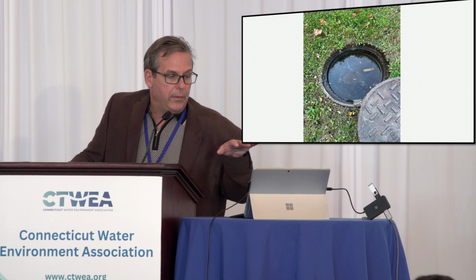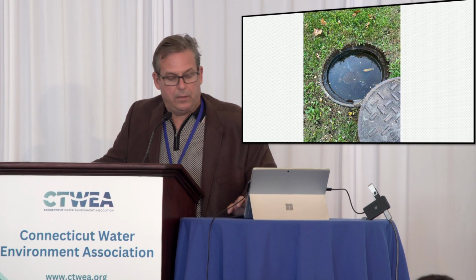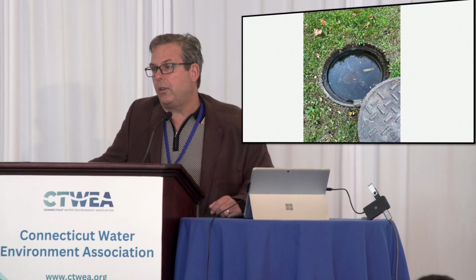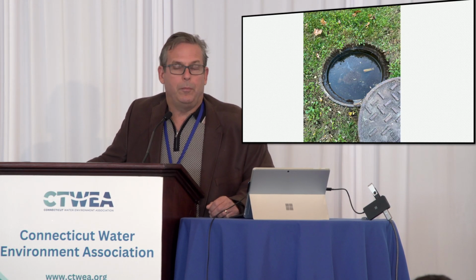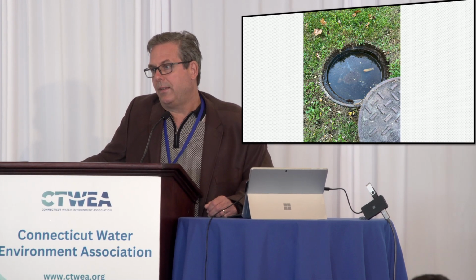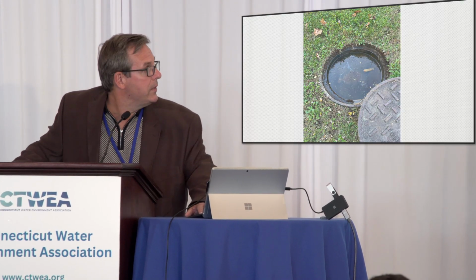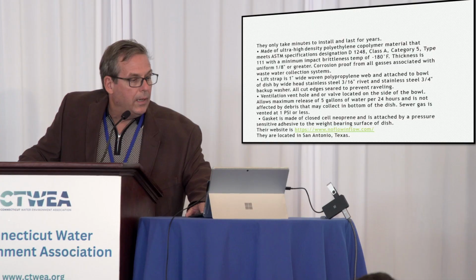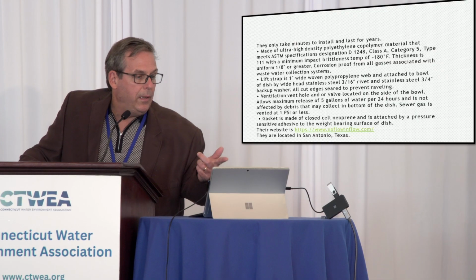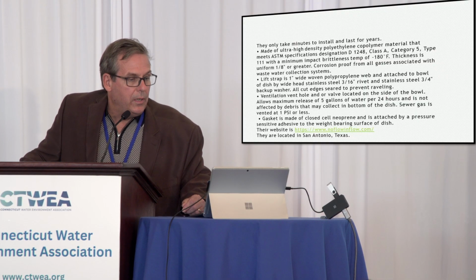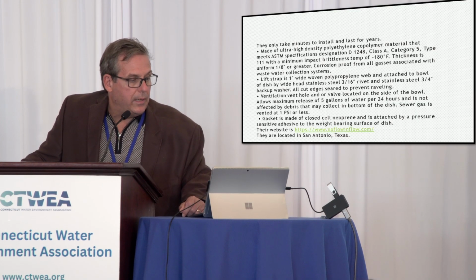So for us, I recently just bought 125, and we put in about 100 so far. We have 630 manholes in our collection system, and I know for a lot of you in this room, you probably have 3, 4, 5 times that as far as manholes. But again, this is a low-cost option that has really worked for us. They take only minutes to install. They'll last for years. They meet the ASTM specifications for structural integrity, and they're located in San Antonio, Texas.